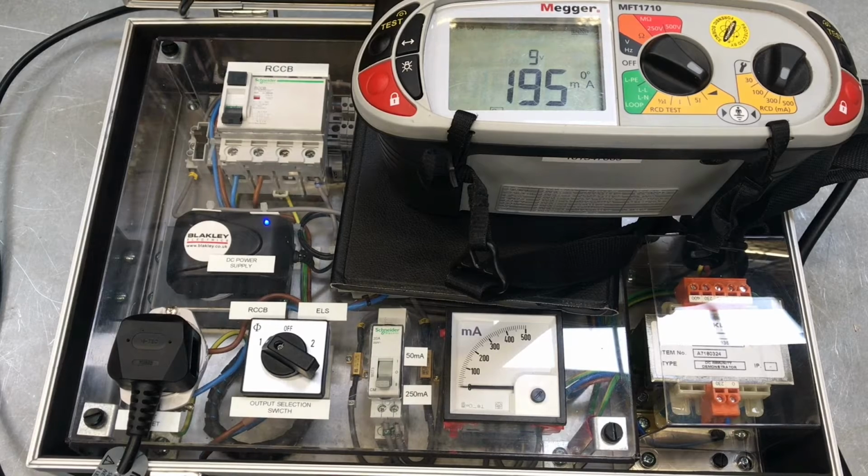Or it may be that someone's run a bond up to the metallic framework of the PV array and there's a damaged cell which is naturally producing DC and leaking down into the earthing system, which, obviously, earth and neutral are combined in some form as it leaves the installation. However, DC does what it wants and goes where it wants. It doesn't perform or behave the same way AC does. So we need to be aware of that.